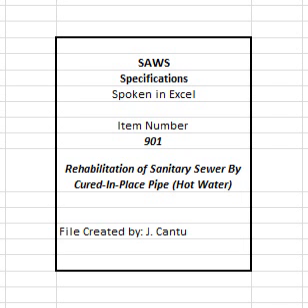F. The wall color of the interior pipe surface of CIPP after installation shall be a light reflective color so that a clear detailed examination with closed-circuit television inspection equipment may be made. G. Seams in the tube shall be stronger than the unseamed felt and meet the requirements of ASTM D5813. H. The outside of the tube shall be marked for distance at regular intervals along its entire length, not to exceed 5 feet. Such markings shall include the manufacturer's name or identifying symbol. The tubes must be manufactured in the USA.